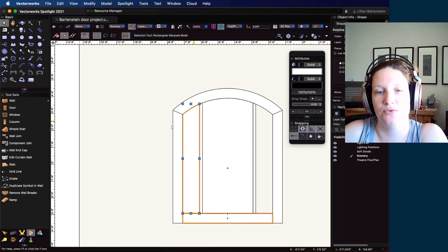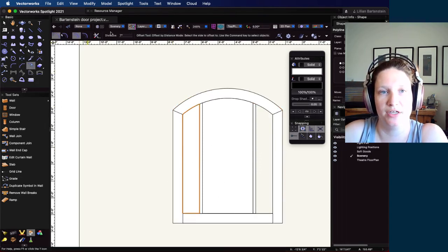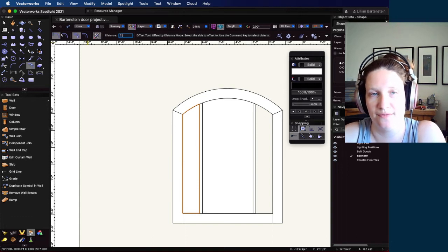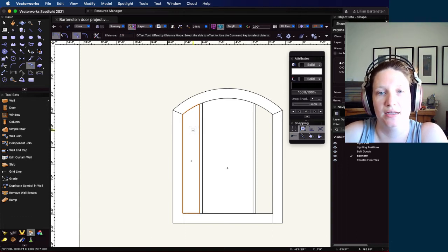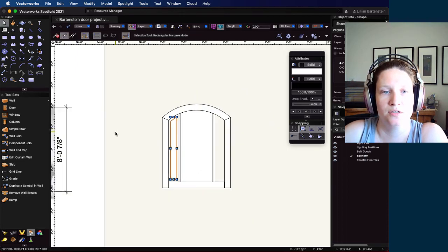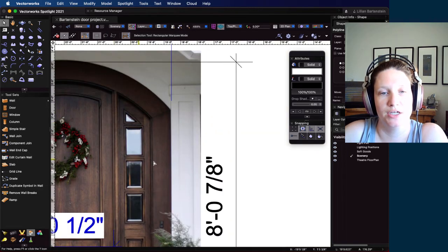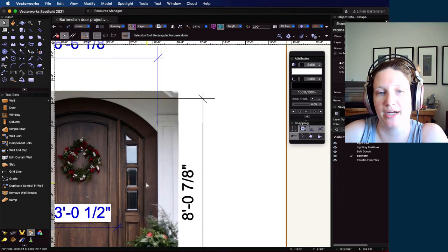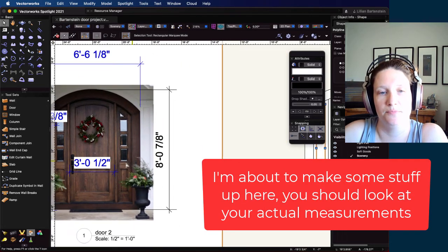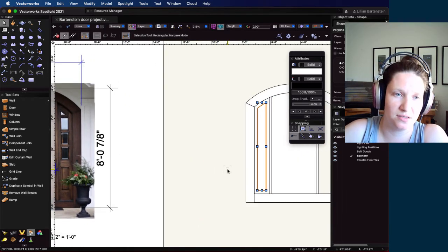So I want to do that first, then I can use my offset tool with that 2.5-inch dimension as the distance, 2.5, and create that interior rectangle, okay? So if you look over here, that's pretty good, right? Now I can just go through, figure out the height of each of these individual windows, put those rectangles in, make sure I put in this last panel, finish out that space, okay?